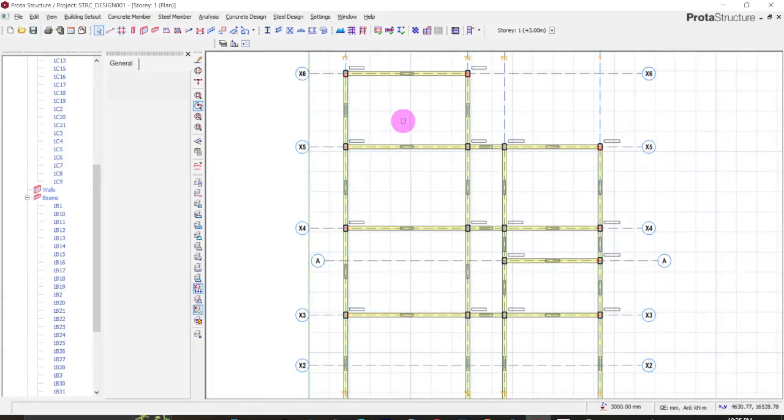Can we leave a wall hanging? Let's say we have a column somewhere in the middle, and then the wall extends up to the end. Can that work? Usually at the end of the wall there should be a column, right? It's not necessary, the cantilever can still support that. The walls will be transmitting the load. Let me just put this in 3D.